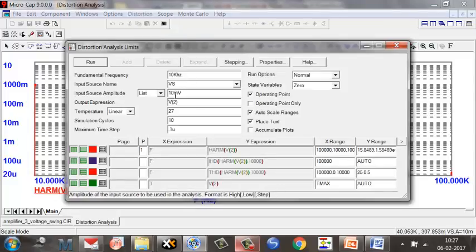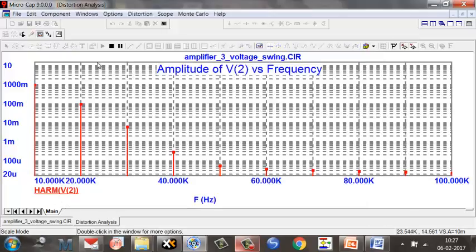At the output, ideally, I would expect 10 kilohertz fundamental frequency. What do I get? I get 10 kilohertz here. Fundamental is right here. I get 20. Can you see here? 20. I get 30, 40, 50, 60, and all that. All the harmonics that are there.